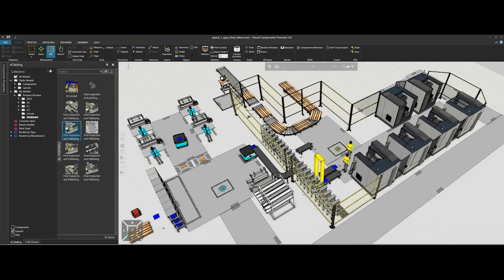Okay. Now, one AGV wasn't good enough. Two AGVs is great. Now, logic might tell you, hey, you know what? 3 is going to be even better. So if we were to add a third one, we would go about 10 minutes into the simulation before those AGVs ended up in a traffic jam that they were unable to get out of based on their movement parameters.